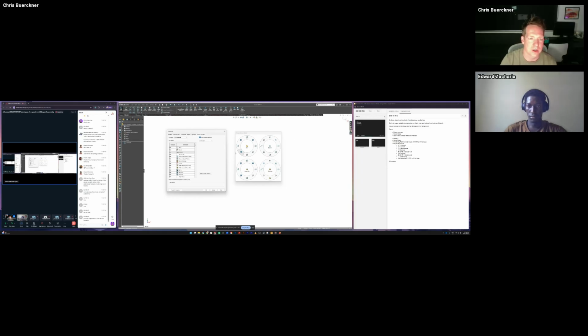You can customize them by searching for, say, a rectangle, and you can see I've got corner rectangle, center rectangle. If I drag that off, that's going to remove it, so I've got an empty slot here. If I want to put something into this slot, I search here for rectangle, grab center rectangle, and drag it over into that slot.